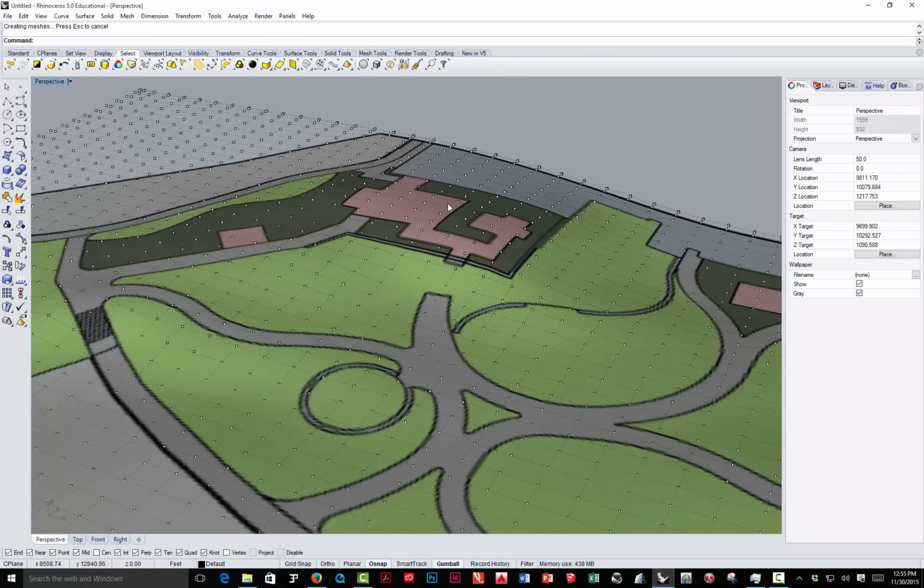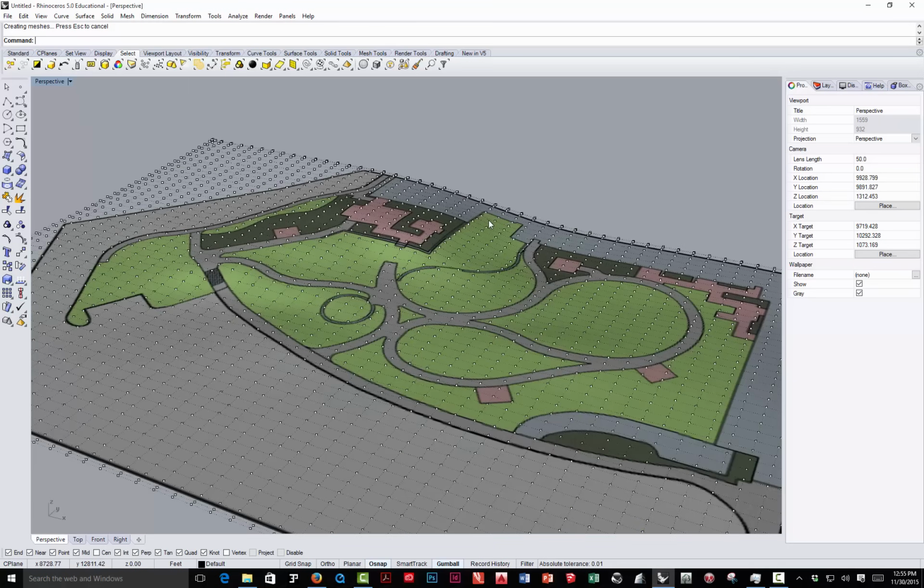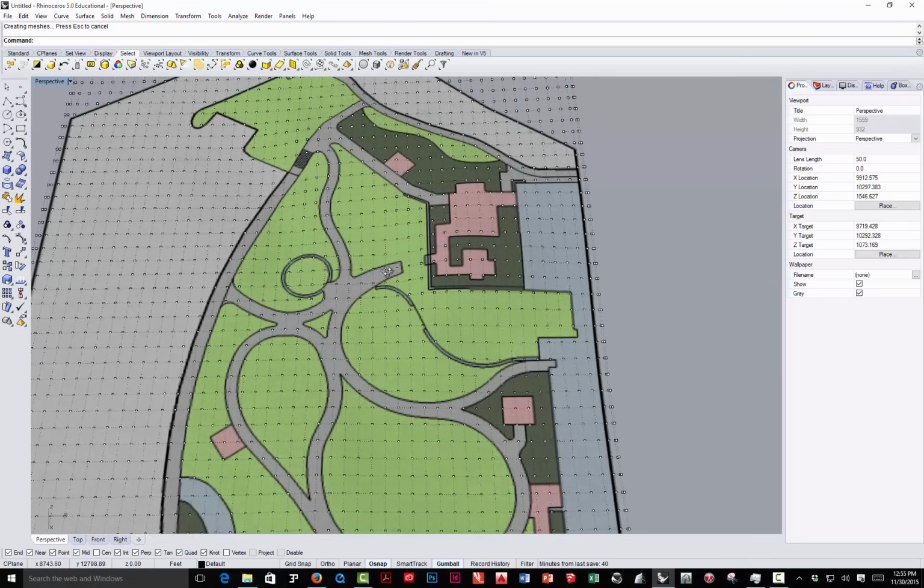Now, I think in class we showed that you could build a 3D object and drop it in there, which you can, and that's perfectly legitimate. But since this ties into a walkway and some other things, I'm going to use a little different method, kind of like the drape command we did in SketchUp when we split, but I went through and used the make planar command in Artisan. This is a similar function that uses the control points within a surface in Rhino.